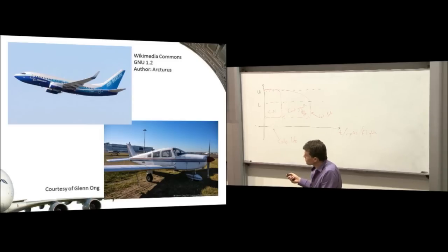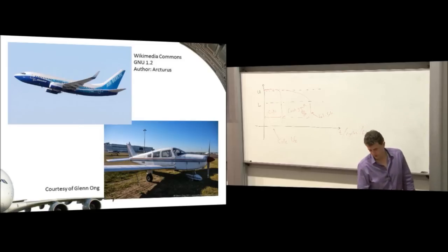Whereas this thing is, as we've already discussed, maybe doing 6 to 12 flights a day, depending on the type of hop it's doing. And it's up and down and up and down. You can understand then that these two are going to have very different requirements in terms of the materials they're going to be made from. This aircraft is not going to be anywhere near as susceptible to fatigue because it's not doing that many flight cycles. It's going to be much more susceptible to corrosion because it's exposed to the elements and gets more moisture applied to it. Corrosion is going to be a bigger issue. These aircraft are doing so many flights that fatigue is the dominant problem. So we have to match materials to the mission.